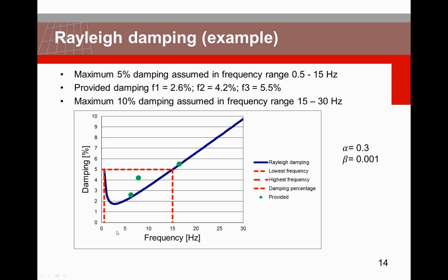Because many people say when applying the Rayleigh damping, you need to take the first 2 eigenfrequencies. That is an option, but in this case we always say that next to these eigenfrequencies, it's always important also to know in which range your loading is and in which range your response of interest is.